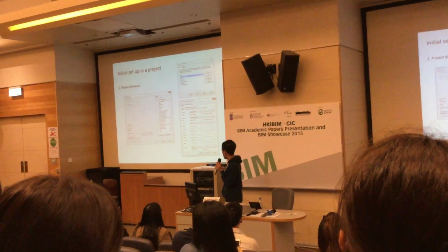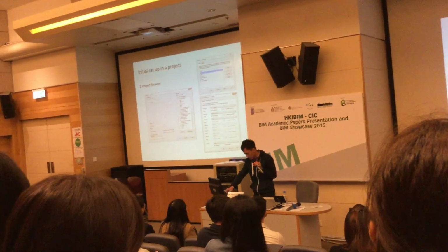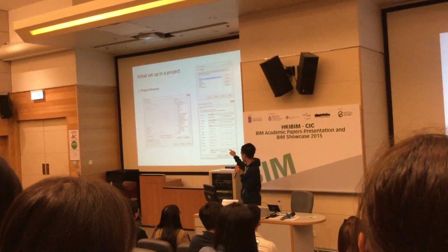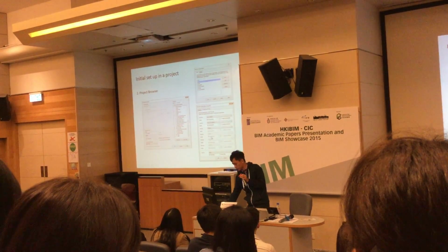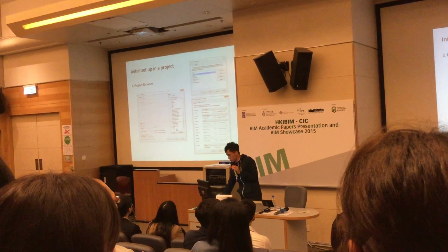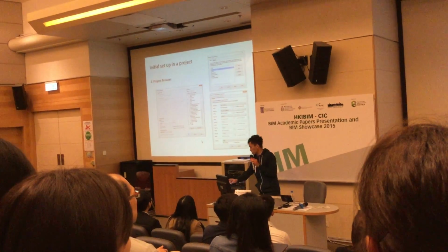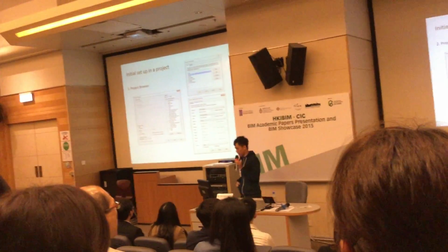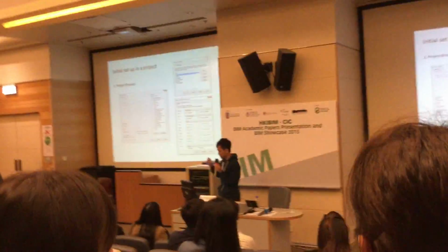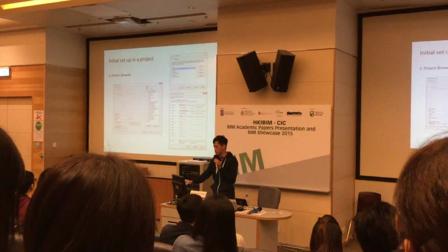I define it as a field category, and then in the type parameters, you choose identifier, and it appears in your project properties bar. And this is the project parameters there on the left. After that, you have to sort it out.